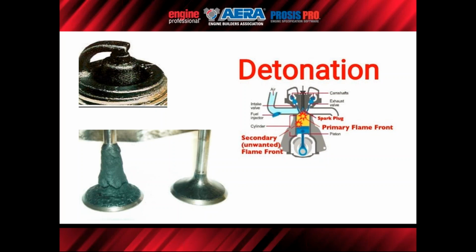There's plenty of opportunity, and we're having to go backwards, like some of the direct injected stuff where they're putting an upstream injector now just to keep the ports clean, and they have a cleaning cycle. Periodically, it'll fire that injector just to wash down the oil in the ports. You see an oil fouled spark plug there, and a good example, same valve dirty with buildup and clean. By the inverted Christmas tree shape on the valve, that's definitely entering the combustion chamber by the valve guide and past the seal.